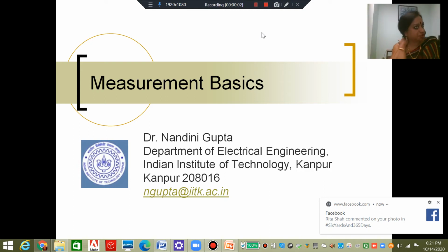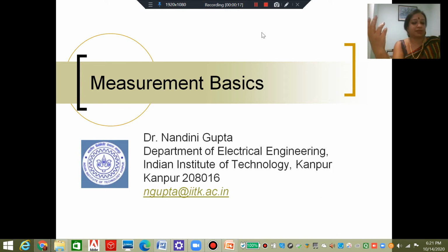So in this lecture, we are going to discuss measurement of high voltage. Once we have generated the requisite high voltage and we have the experimental setup in place, we need to measure what voltages we are applying across our insulation. If we are doing a disruptive voltage test, at what voltage does the breakdown occur? Therefore, we also need to measure the high voltages that we are working with.